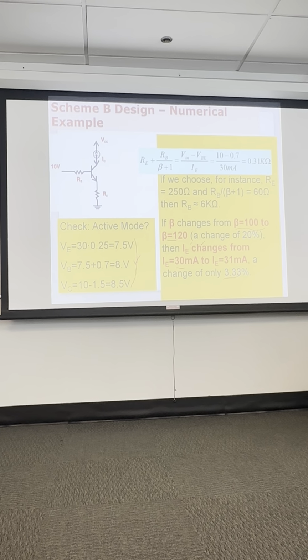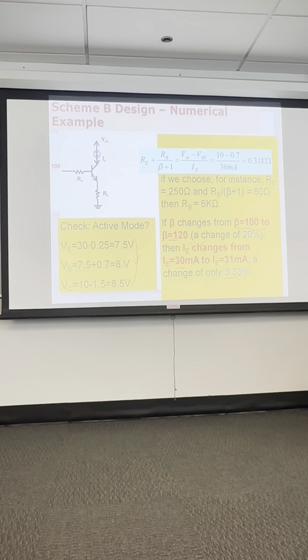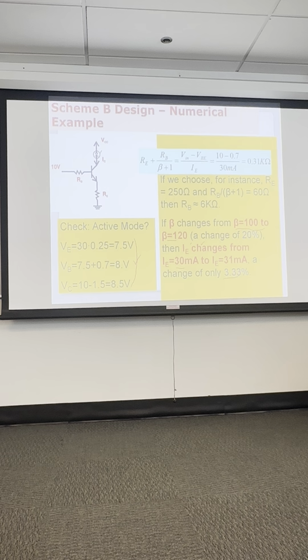Now the other part of manufacturing this circuit would be the LED is going to have a variation in its turn-on voltage. So you probably research the LED foundry and get their PN junction variation. And there's also temperature and other parameters. We're just assuming whatever happens, it's only beta that we're concerned about.